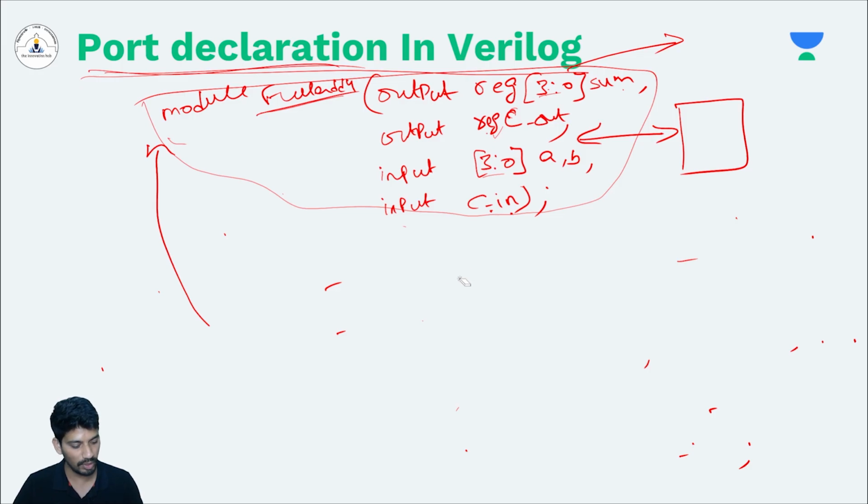So if you define them using the register data type, it is an illegal statement, because you want the input or in-out port to start working as immediately as possible. So you should not define them with the register data type, you have to define them with the wire data type.